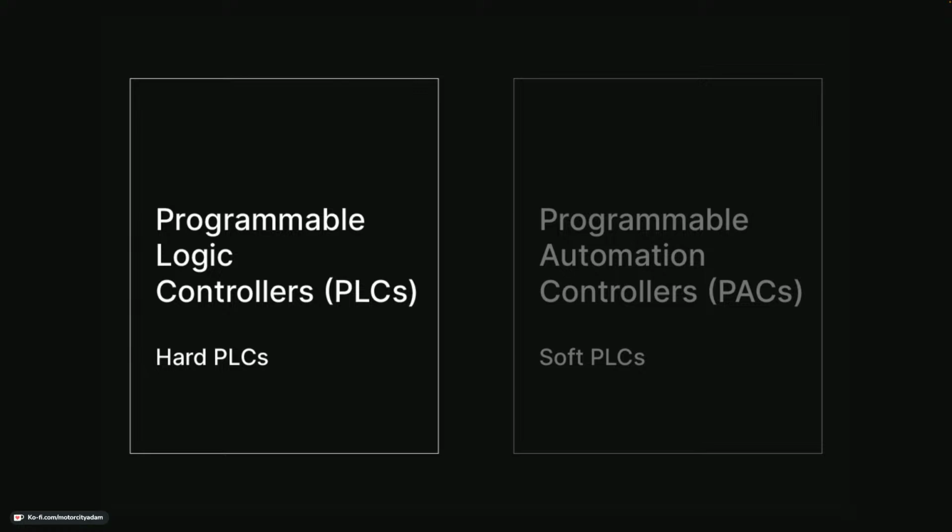CNC, they usually include a CNC motion control package that can read in G-code files and output. So if you're doing a custom vertical milling center or something, and you're designing that kind of machinery, you can slap on a programmable automation controller and get that CNC functionality, quote unquote, for free. I mean, you're paying for it, but it's built in, or it's otherwise compatible with the programmable automation controller.